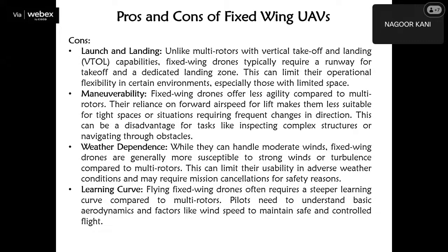I explained weather dependence already. They can handle moderate winds, but they cannot handle strong winds and turbulence. So multi-rotors have the advantage there. And the learning curve. Assembling, dismantling, and flight control maneuvers are very complex compared to multi-rotors. The learning curve for operating it takes a longer duration compared to multi-rotors. So more skilled manpower is required. That is the con.